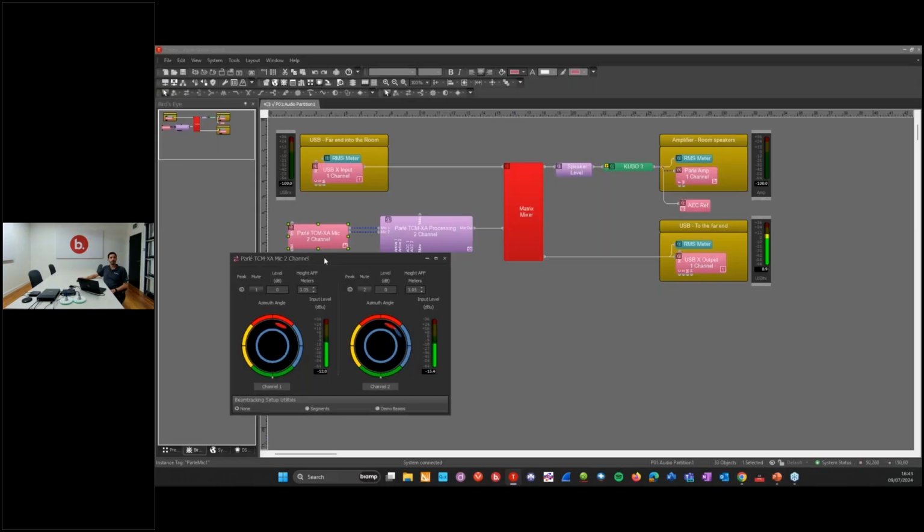If you need to, you can manipulate that value slightly. If you want to bring the coverage cone in a little bit tighter or a little bit wider, you can manipulate that in the height above finished floor setting. Now in the mics themselves, in the X series microphones, we have the ability to turn on and off segments. So in the room here, we've got a doorway behind me. We might want to stop the microphones from tracking in that angle. And we can do that quite simply.